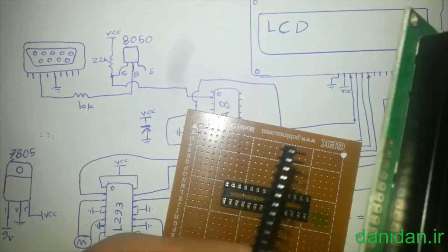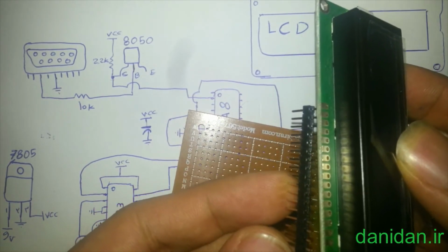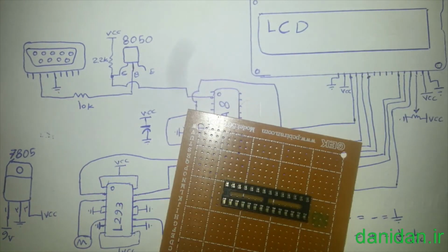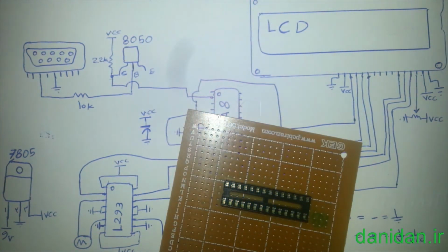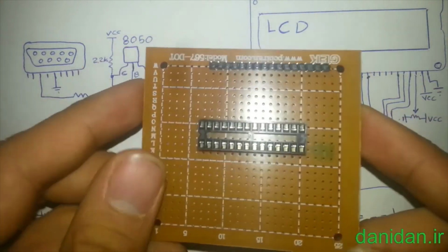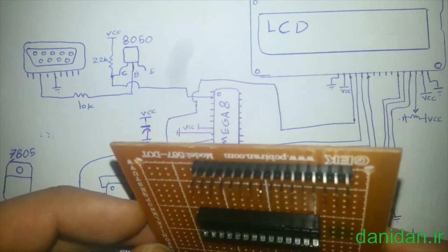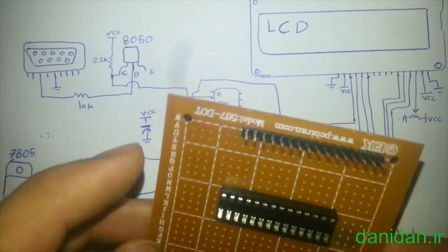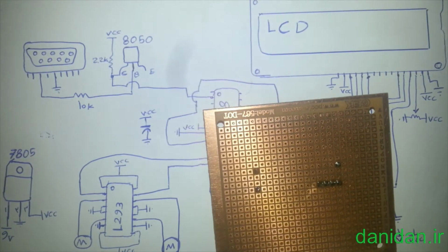so to connect the LCD to the board we need the pin header. I just try to cut the pin header. Each character LCD has 16 pins, so I try to put the LCD there. I try soldering them just like that.